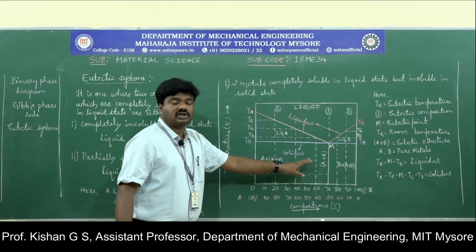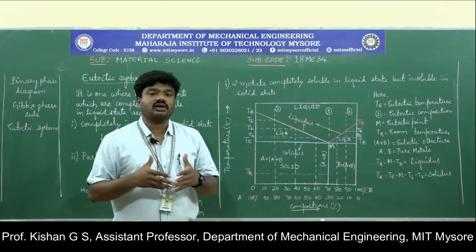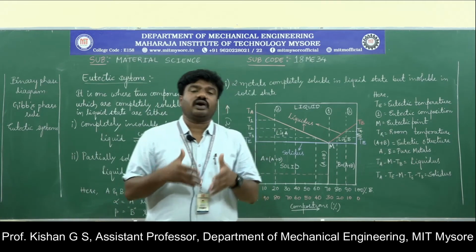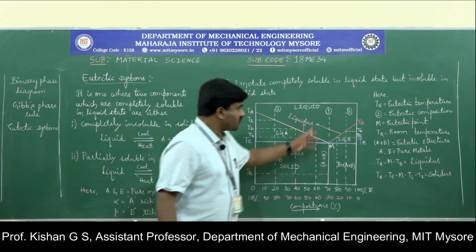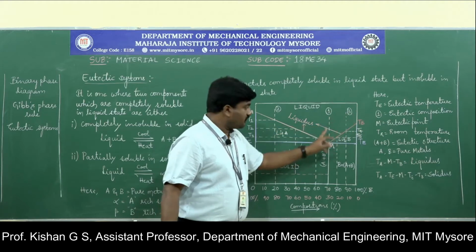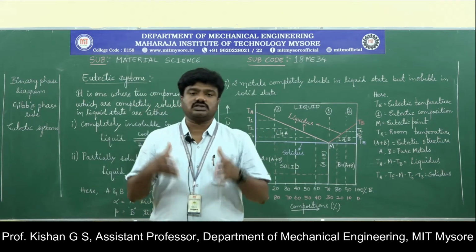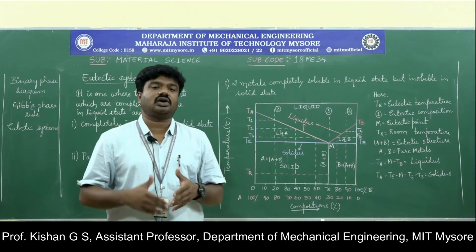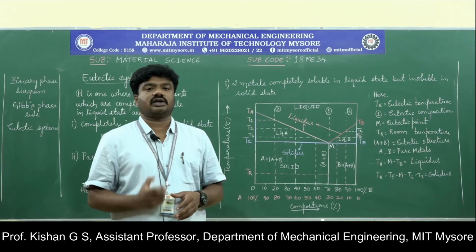That is the combination in which both the pure metals combine together or solidify together while being completely insoluble in the solid state. Hence, that is the composition to be referred to as the eutectic composition, the point at which both the pure metals meet to initiate or completely solidify. That particular point is called the eutectic point.